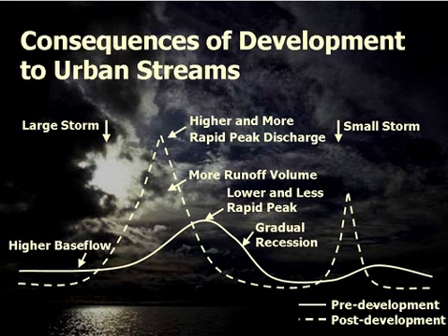Now, next, we have two graphics that you've probably seen before, and Neely can help me explain these. These are generalized, sort of artistic, if you will, depictions of what happens in a watershed as we increase the impervious surfaces. And, Neely, do you want to explain this first graph a little bit? Sure. We'll just quickly summarize what you're seeing on your screen, Nikos. The solid line represents how a stream flow would respond to a storm event prior to its development. So you have trees, you have lots of pervious surfaces that are absorbing that rainwater into the ground, recharging that groundwater. And so you really don't see that surge of stormwater entering the stream quickly and in large volumes.